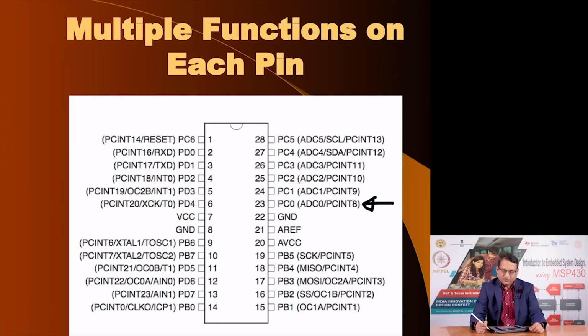It also offers you an interrupt on this pin called PCINT 18, and you want both these functions at the same time. Now, the way they are mapped on a single pin, it will not be possible,